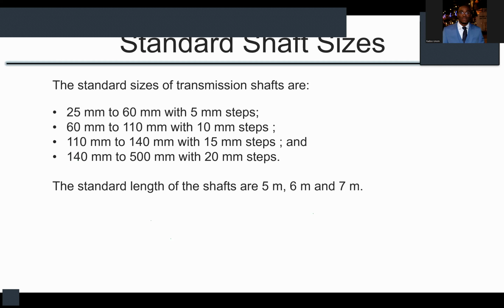When you have calculated and you have an answer, you then come to your standard shaft sizes and select a shaft in line with what you've calculated. What you have calculated gives you the minimum size required to transmit the amount of force that you want to transmit.